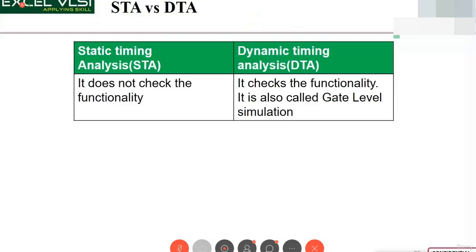Now you saw that if those delays are more, it will spill over to one more clock. At that time, fixing that could be increasing the clock period, that is lowering the frequency of the circuit, right? So that could be an easier fix, but otherwise you don't want to reduce the frequency. It is designed to be working at that frequency. Then you will go for other optimization techniques to fix setup and hold violations.